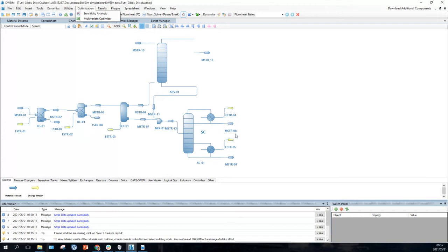And the methanol in this flow sheet comes out at the top of the distillation column. And we're going to just see what temperature we should design to, so that we can get the most methanol. And there we're going to just use the thermodynamics at temperatures high enough where we know it's going to be at equilibrium. So let's go and start the sensitivity analysis.